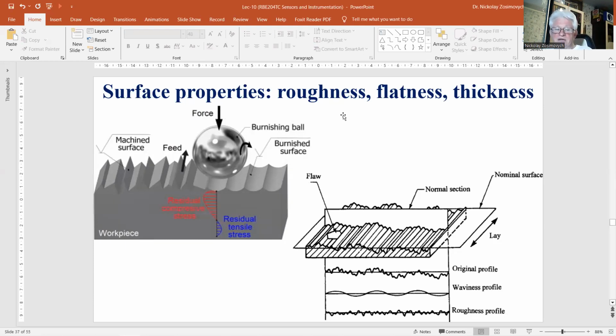The roughness measurement is based on the scattering of a light beam incident normal to the surface. The height measurement follows the standard triangulation method. A linear photodiode array is used to determine the position of the reflected light. With this system, roughness can be measured over a range from 5 to 100 nanometers. The height range amounts to plus minus 300 micrometers.